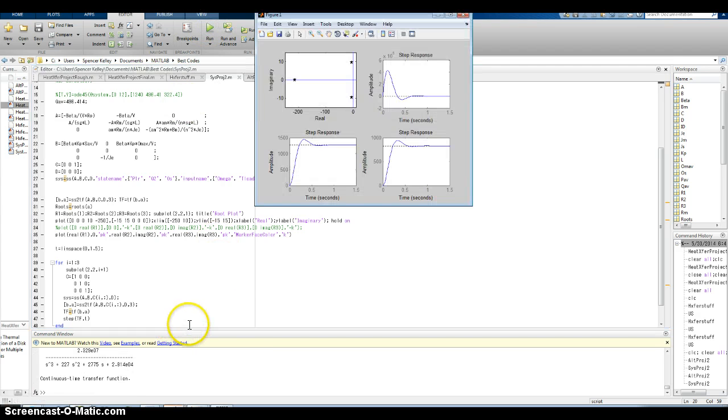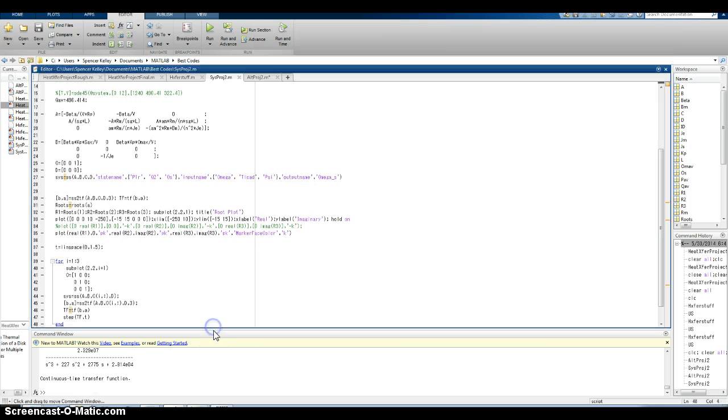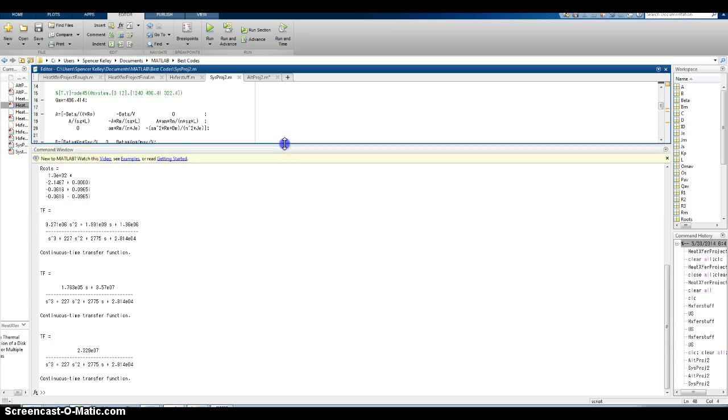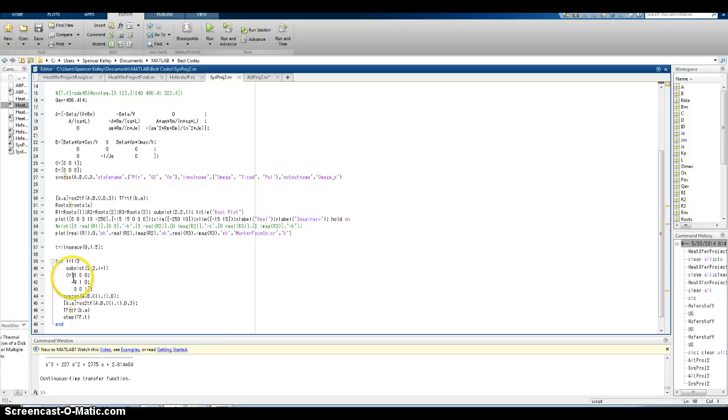the gist of the program and of this script, and there's that output response again. But it's coded to where you can see there are 3 transfer functions. What these transfer functions represent is the lever input to each of the outputs, where you can see this C matrix is found within a for loop, to where it's identifying either the pressure through the capacitor, the flow through the inerter, or the spindle speed as the output that is under consideration.